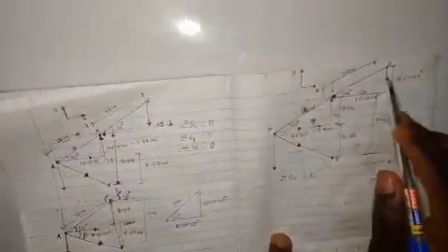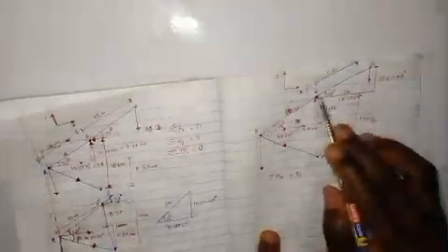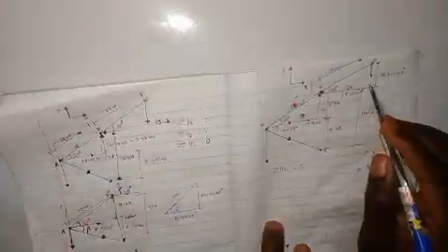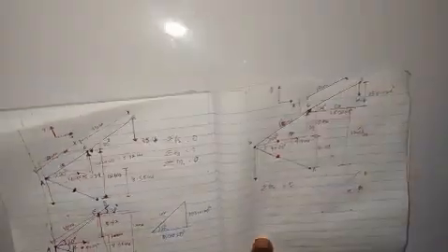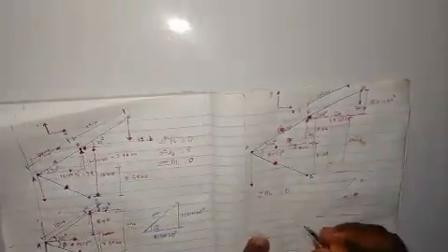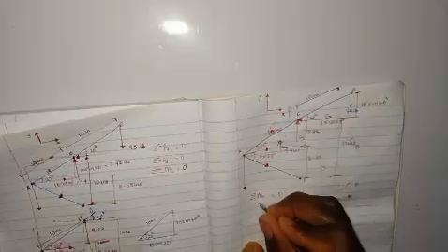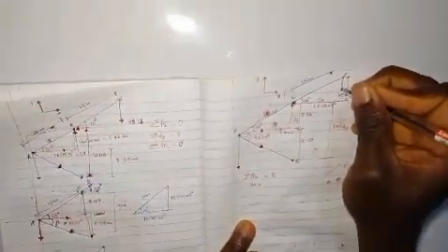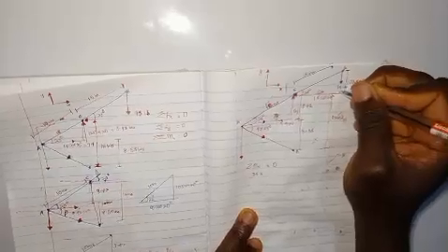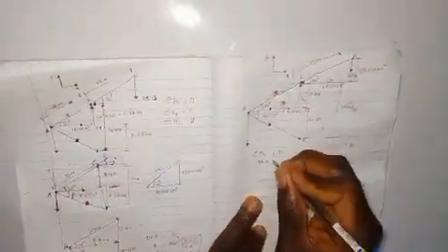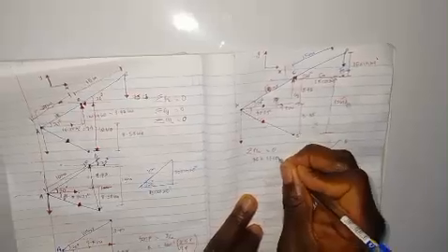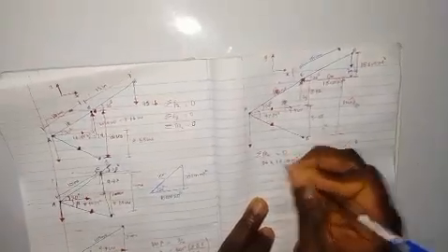So now let's take B with respect to C. Don't forget, here we have 75 pounds. So here we will have 75 times, this is the force. The force can be extended, so the perpendicular distance of this force with respect to this is 15 cos 20 degrees.